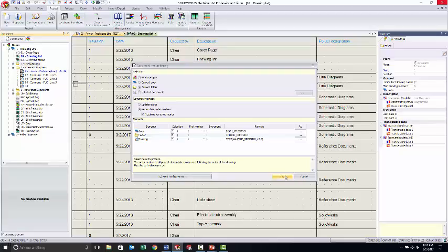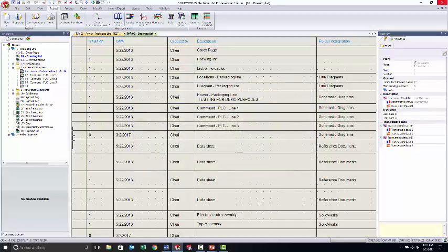So how do you fix it? Now all you have to do is recalculate the order number based off of what you are selecting. You can either select the entire project, a book, a folder, or just specific documents. Shuffle it the way you want it, hit whole project, and then Okay. That way your PDF will come out in that same direction, because before you could actually have those shuffled incorrectly, and even though you have them in an order here, if you by chance moved something, what would end up happening is it would not.